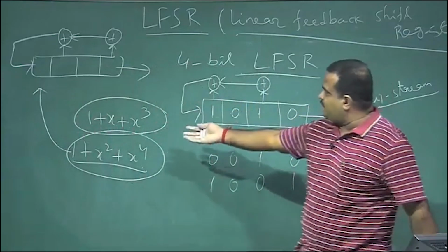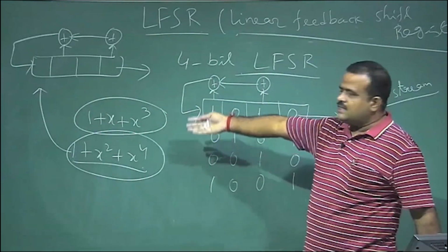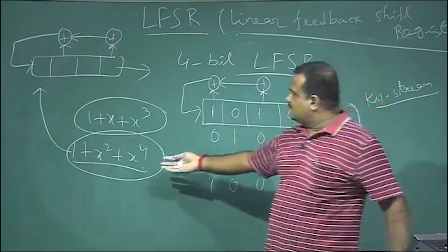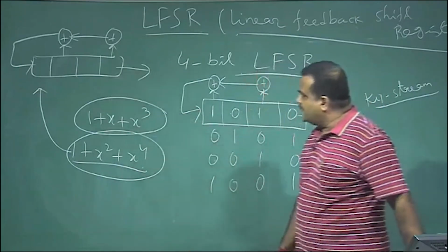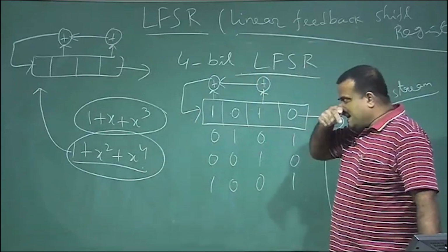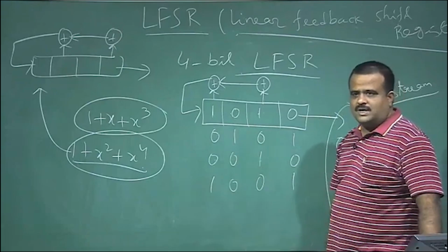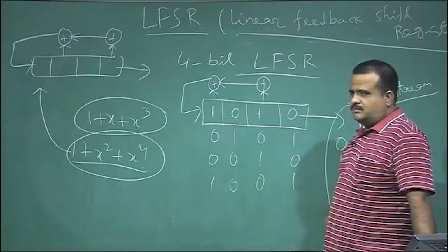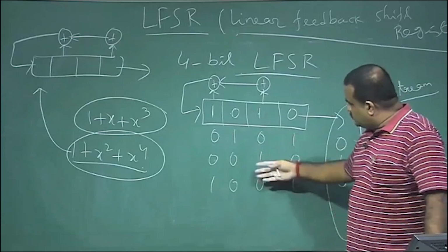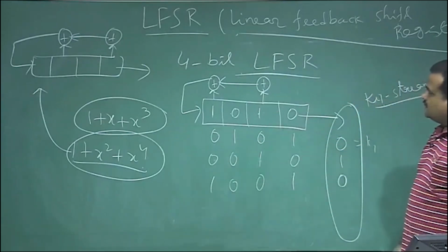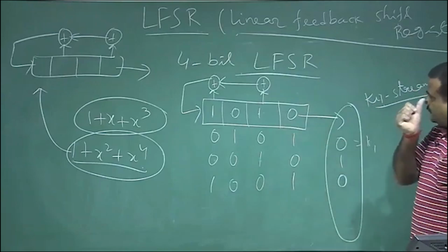So, if we have an LFSR, we can have a degree-4 polynomial, or if we have a polynomial, then we can construct an LFSR. Okay. And if this polynomial happens to be a primitive polynomial, we will talk about primitive polynomials, then this will give us a full sequence, the period of this will be full if this polynomial is a primitive polynomial.